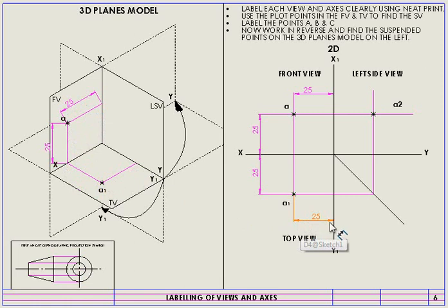The extra bit of information that they did give us is that I have actually measured 25 millimeters away from the x1, y1 axis. So if you want to double check, you can simply go and measure 25 millimeters away from this xy axis. Alright, there it is there, that line. And now I have found the A1, the point that is actually on my horizontal plane, the actual surface.